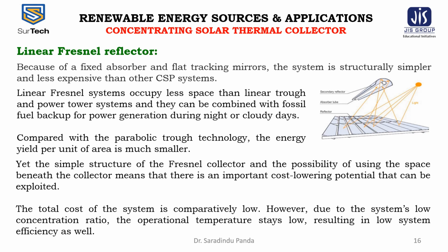The total cost of the system is comparatively low. However, due to the system's low concentration ratio, the operational temperature stays low, resulting in low system efficiency as well. The disadvantage of the linear Fresnel reflectors having only one receiver is that it is difficult to change the receiver's direction for a large size of the field required in a multi-megawatt power generating system.